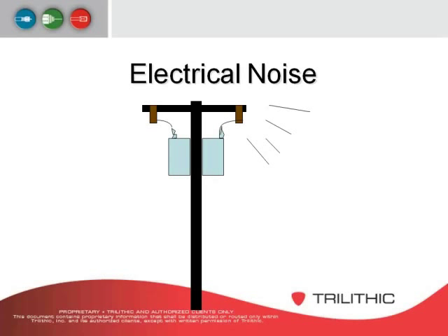These types of things create electrical noise, and that electrical noise goes across the spectrum, but it can be detected in the areas where you're doing signal leak detection. So there are times your leak detectors will go off, and you'll think, I know there's not a leak here. I don't even have cable at that location, but it could be because of electrical noise.